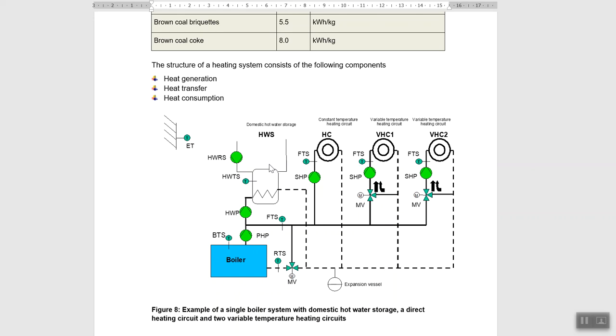And then you can see the DHW tank with a temperature sensor inside of it, and the pump to make the circulation. Okay, great. Also, with the output from the boiler and the return to the boiler, we have the temperature sensors to make the best decision for this motor.